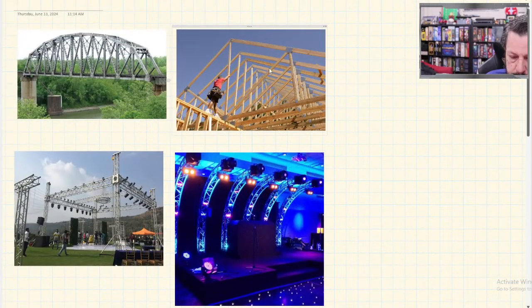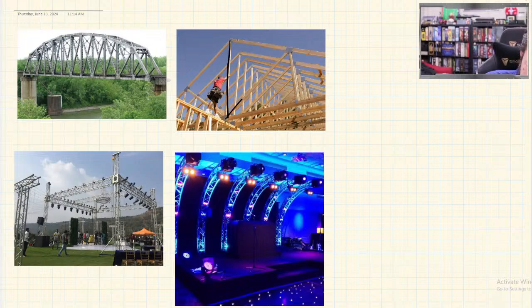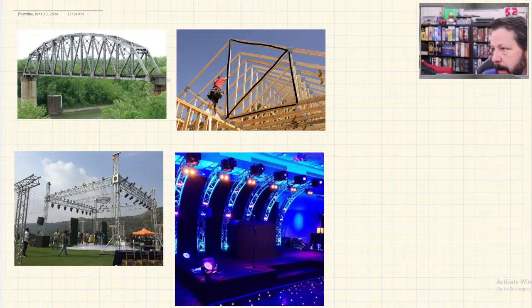Here, there's a triangle, that's a triangle. Then here's another triangle. And then off the page are more and more triangles. So trusses are divided down into triangles. And if you think about it, a triangle is not able to be reshaped in any way. If I had a square, then there are enough degrees of freedom where I could physically build that square.